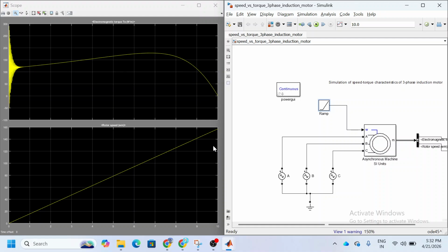When you put a bike in fourth gear or fifth gear and you are moving at a low speed, that is 20 kilometers per hour, the bike will not move smoothly. It will turn off suddenly and make some other sounds like that. Because there is very low torque at higher speed. For slow speed there will be high torque. When we require torque, we will switch the vehicle to second gear, third gear. When we require high speed, we'll switch the gear to 5, 6, like that.